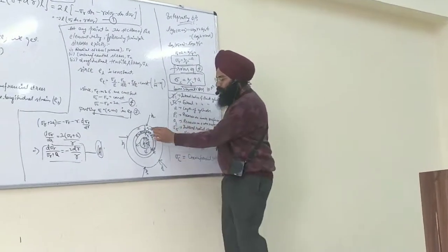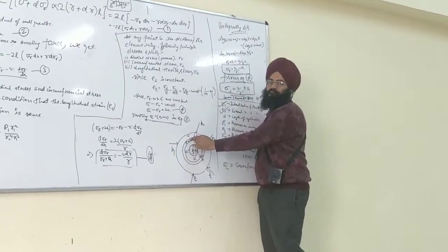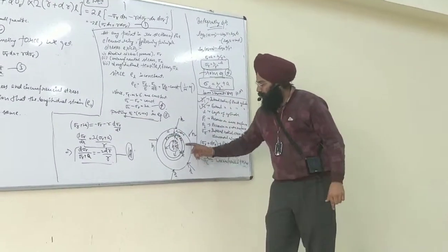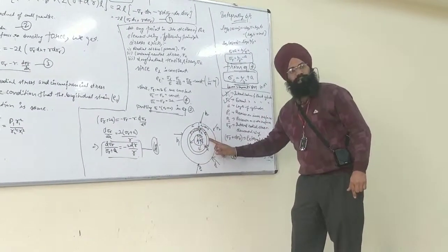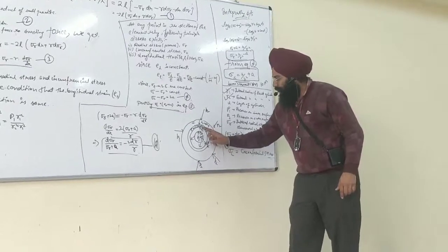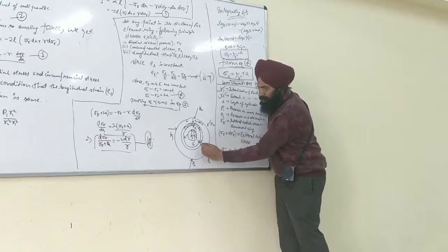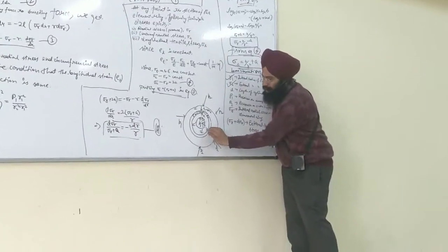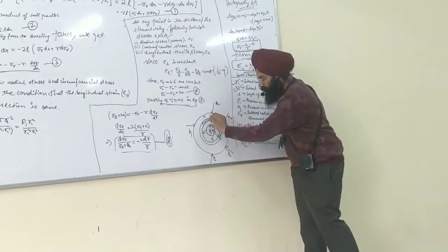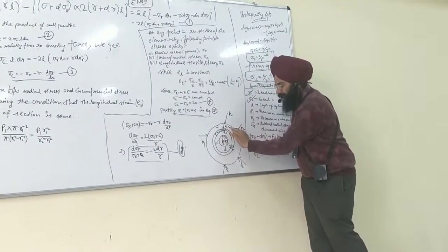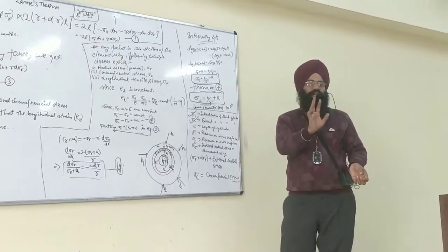Now let us assume a small section on the surface of the thick shell on the circumferential face. This will be your circumferential stress along the circumference. On this surface you have a small width, dr, and you also have the value of the radial stress, that is stress r plus dr. So now on this surface I have taken three values.